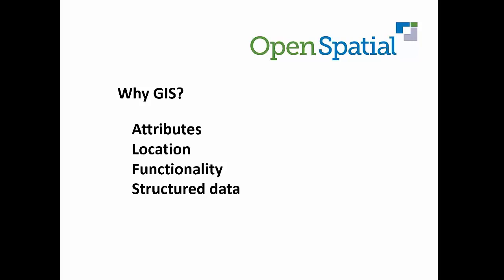In GIS, the data is more structured. In CAD, you've got layers, layer names, line styles, symbology, and that sort of thing, but it's fairly inconsistent. One person's drawing will be different to another. In GIS, typically the information is stored in a database, and it has a particular structure. Entities are split into points, lines, and polygons as geometric primitives, whereas in a CAD drawing, on a given layer, you may have text, lines, polygons, hatches, dimensions, and so it becomes a little more difficult to structure that.